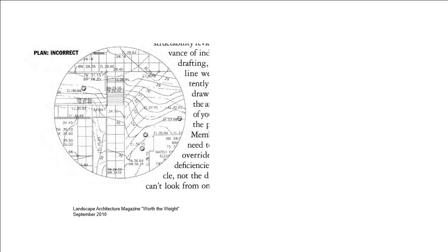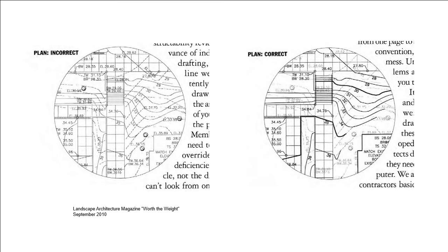And again, here's an example of a drawing that has no line weight variation compared to a drawing that has good line weight variation. You also need to know that when you're working in AutoCAD, to see this line weight variation, you're going to need to create test plots, or PDFs in this case, so you can see what you're doing. It is a good idea, in fact it's paramount, that you make these test plots and PDFs early throughout the whole process. Do not wait till the drawing is finished to see what it looks like.